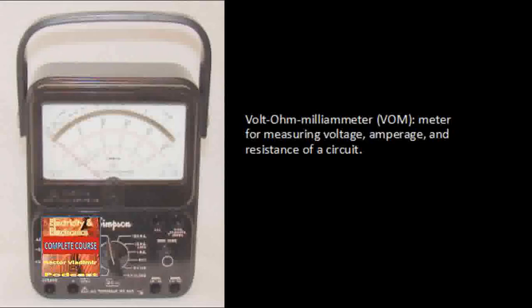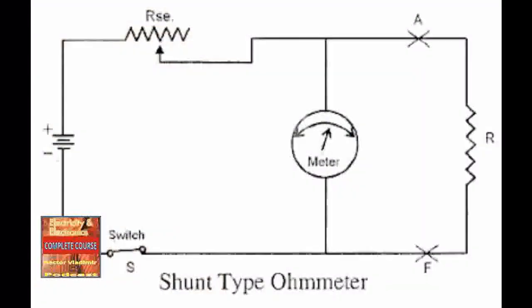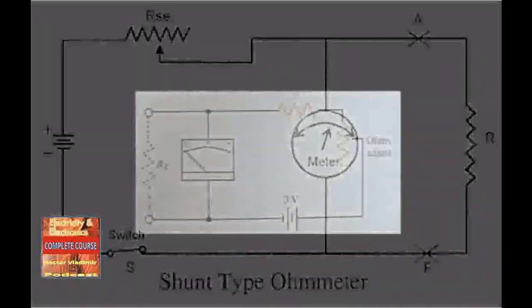Caution. Before connecting an ohm meter to an electrical circuit to read an unknown value, be sure that the circuit is not energized. An energized circuit will damage the meter and can be harmful to you. Electrical energy in a circuit is not needed to operate the meter movement coil, as it is when using the voltmeter or ammeter. The batteries inside the case provide the source of power for the ohm meter. Connecting the ohm meter to an energized circuit will apply the circuit's voltage directly to the coil and battery, which can result in damage to the meter and possible harm to you.